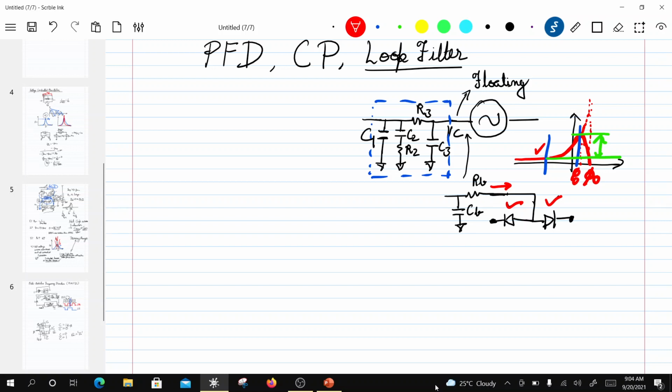So there is always a droop at low frequency, and we have to take care of that droop. One way is I have some form of a buffering mechanism over here. If I have a buffering mechanism, I would be able to supply current and still hold the voltage constant here, so that the VCO doesn't change the frequency. So this we have to be careful of.